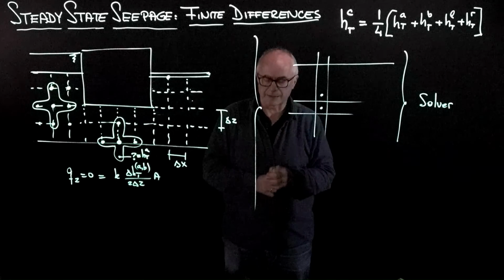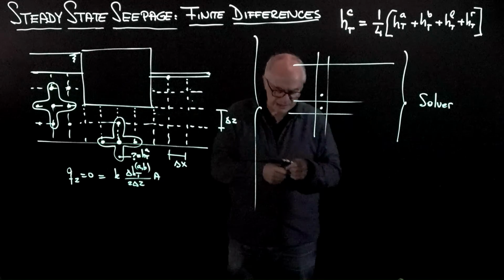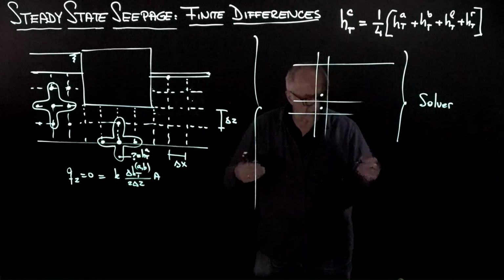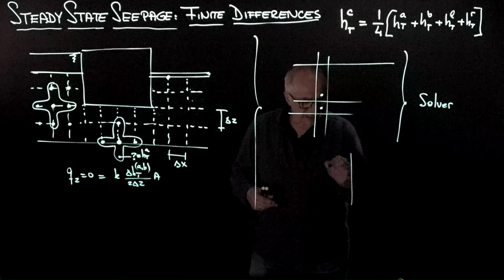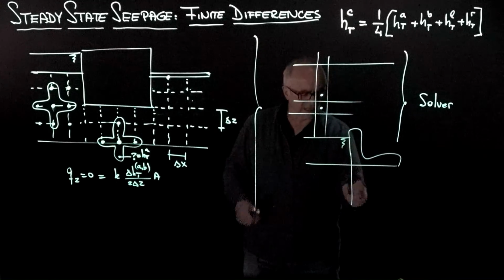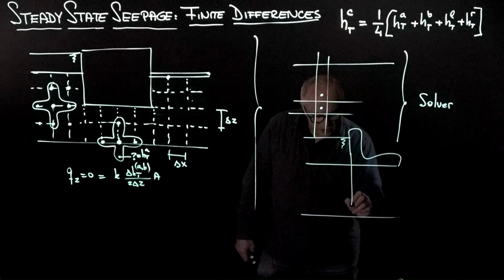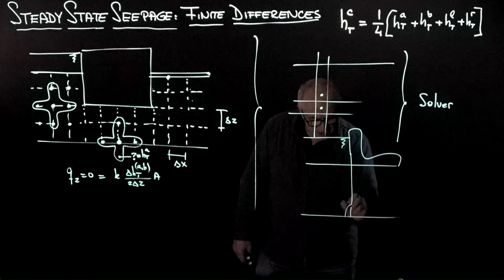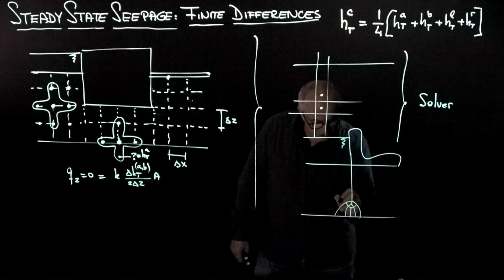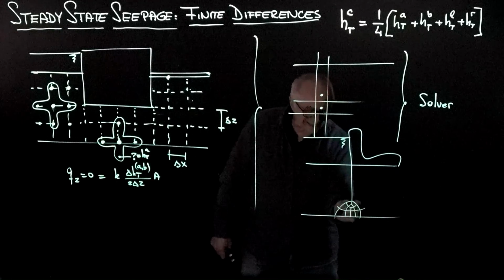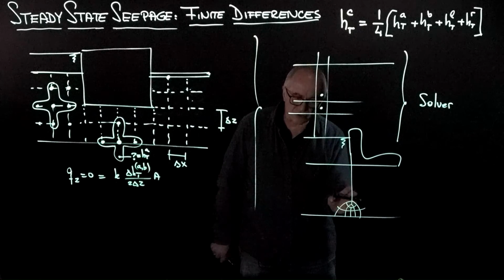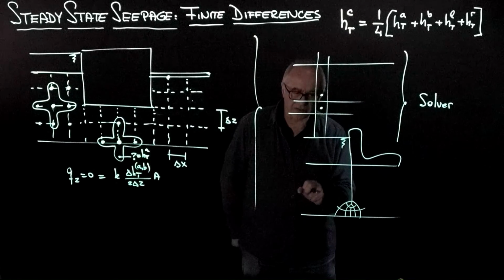The last point I would like to make is this. If you remember the case of a flow net, and when we are near an intersection, this is the typical drawing that we do for flow nets in seepage. When we draw the flow net, there will be a large number of equipotentials here because the flow strangles itself, and so the delta x and the delta y will have to be small near constrictions where the gradients are going to be very large.